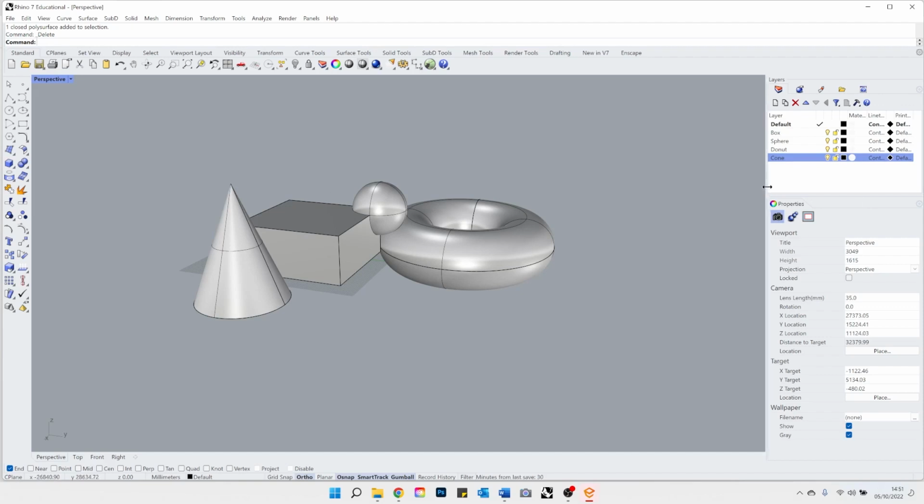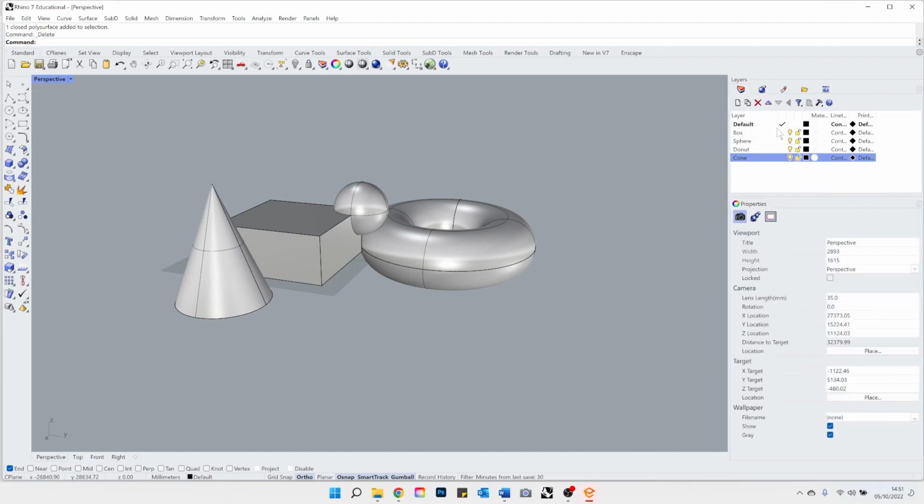So where you have your layers, there are a couple of options. You can either set it up to be default, so it has this little tick next to this layer. If you know that in the next half an hour you're going to be working on windows, you set up a separate layer called Windows, you can make it default, and it means that everything that you're going to create at this moment is going to appear on this layer that you have just selected. By double-clicking a layer, you can change which one is the current layer you're working on.